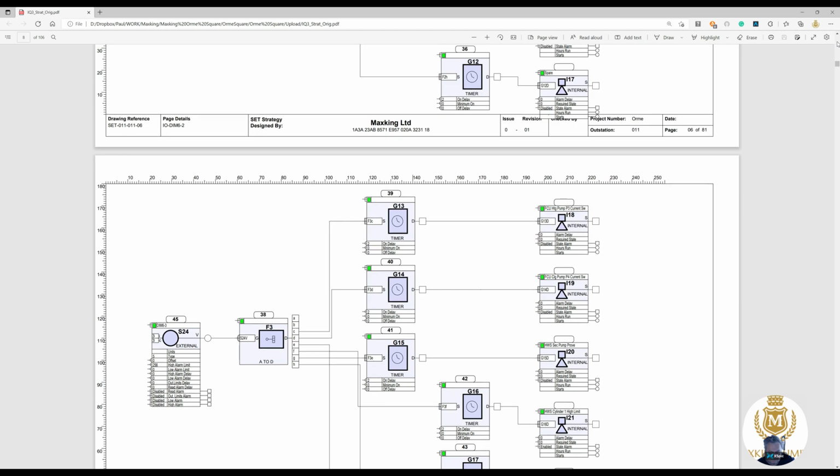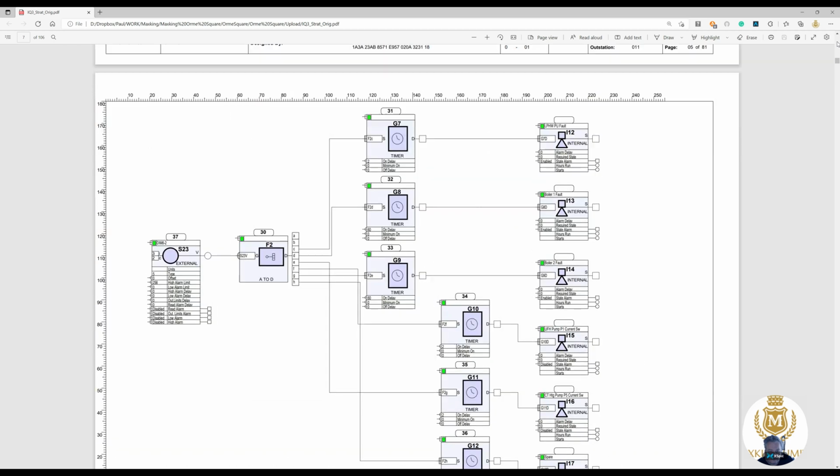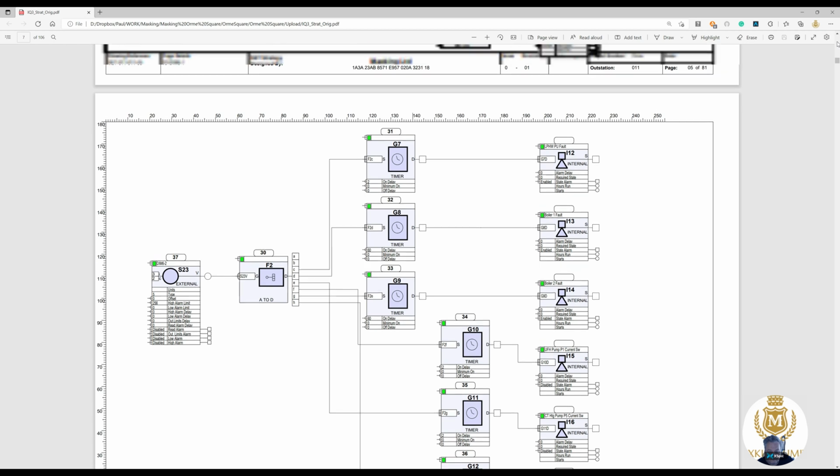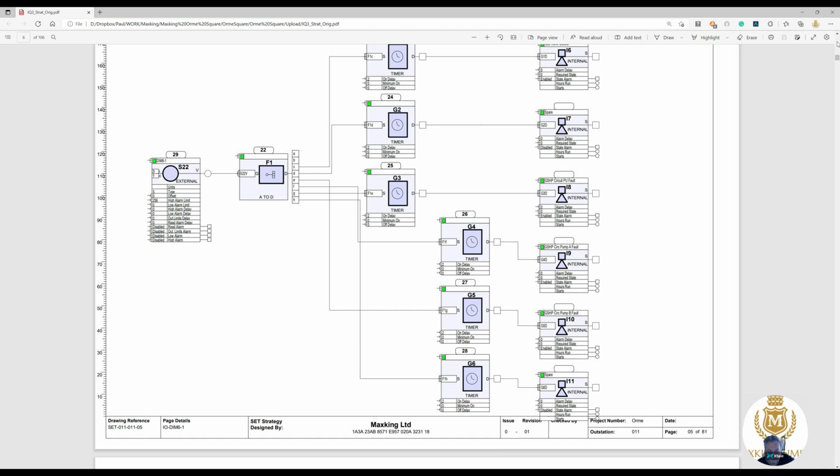DIM 3, not interested. DIM 2. Do I want the LPHW PU fault? Well, if I do, I can take it via network, so I'm not interested in that. This would be the one: ground source heat pump circuit PU fault, so G3.